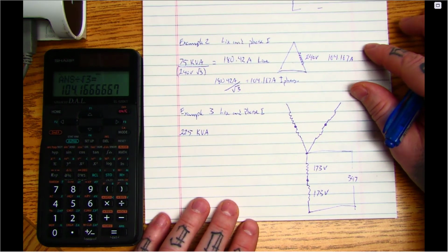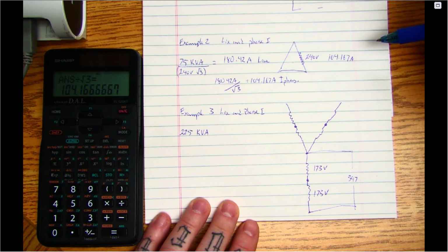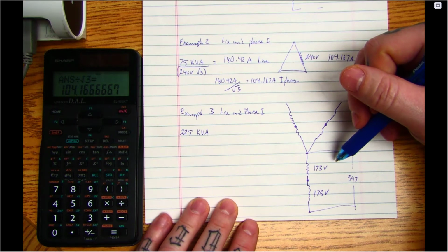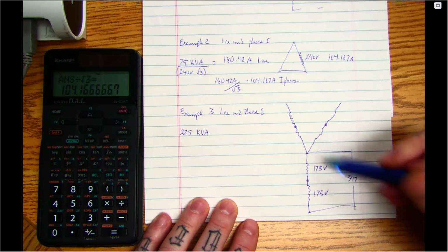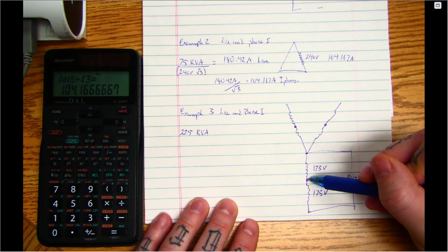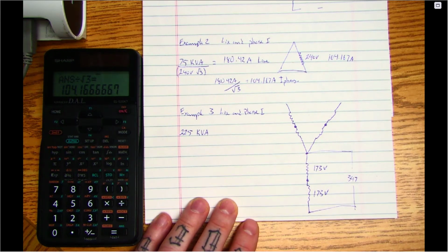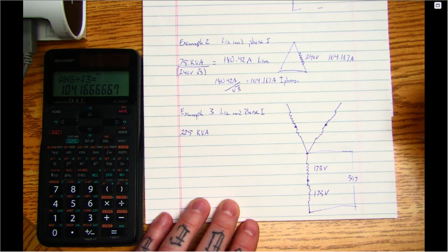So now the next one talks about multi-windings. It's kind of a nice review of Y and delta theory. This one we have multiple windings, so we just want to see what happens per winding in this scenario. They're saying that I got 347 on a phase level. Well, if these are hooked in series, I know the voltage is going to split. They're going to be exactly the same winding, so they're going to share the voltage evenly. Now, what's the line current and phase current? We can find that out too.